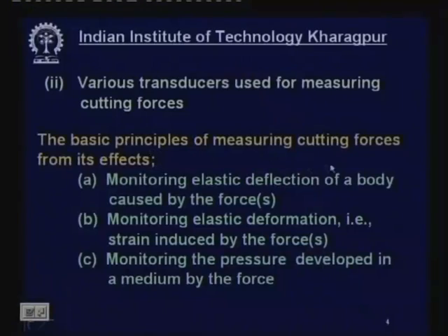The basic principles of measuring cutting forces: it is understood that cutting force, which is the force, has to be measured from its effects. What are the possible effects suitable for measurement of cutting forces? The basic principle is monitoring the elastic deflection of a body caused by the force. Here is a beam, suppose an elastic beam, and it is subjected to a force. Due to the force, it will undergo bending or elastic deformation or deflection.